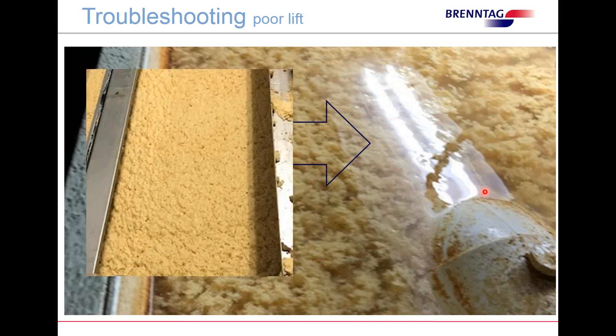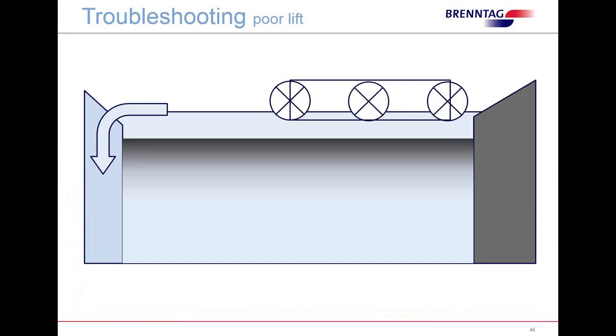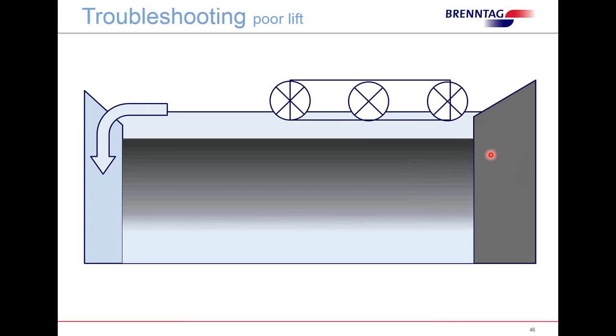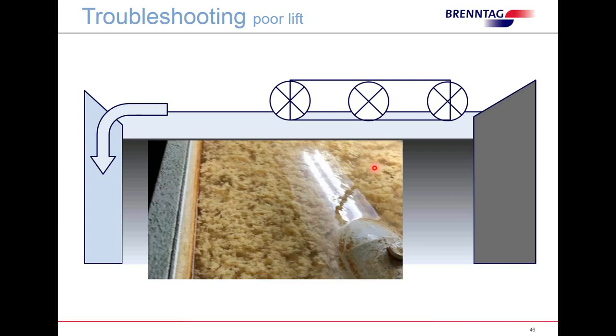And again, this is what it should look like, but look what we're getting. Look, there's hardly any water on the top here, but here, clearly we can see the light from the ceiling. So just to give you a little bit of a depiction: if you are not taking a sufficient amount of sludge off, and you're allowing a lot of sludge to stay in the system, your sludge blanket can continue to grow, causing major problems on your discharge. So it's just something to consider. Again, we really don't want to see that situation in our DAF unit.